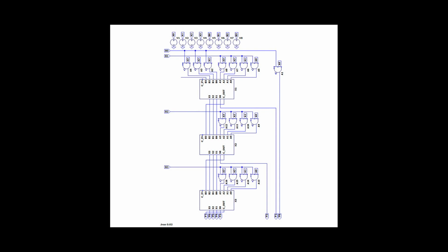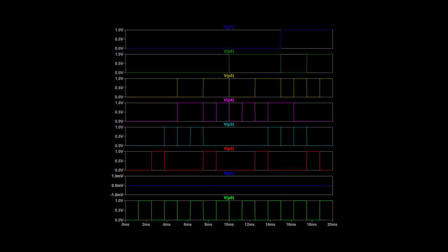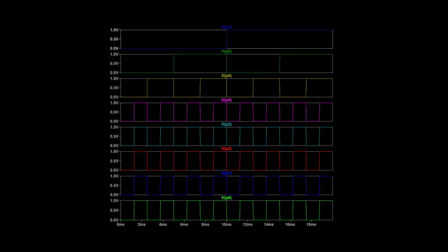Besides, in binary multiplication, there are 2 steps, which are single bitwise multiplication and adding all partial products into a single product. The partial product is produced using AND gates. The number of AND gates in a 4x4 multiplier can be determined by taking the product of multiplicand and multiplier bit sizes, which is 4x4 equal to 16 AND gates as shown in the figure above. Then this is all the input and output of this 4x4 multiplier.